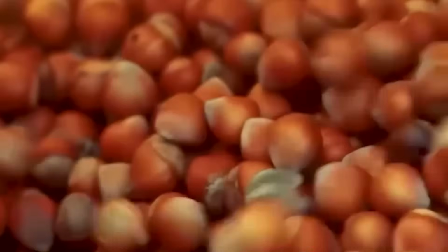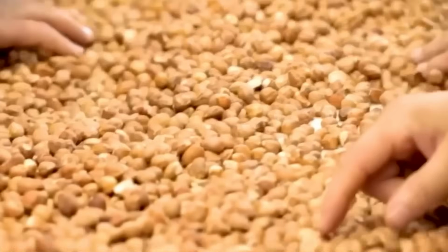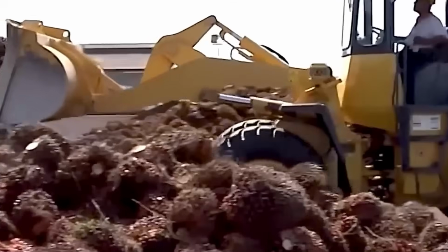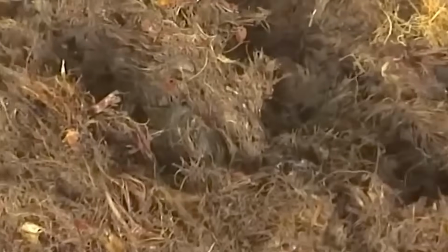Grouping is performed using star wheel collators, which align the units into rows for secondary packaging. Secondary packaging uses flat fold cartons erected via vacuum cup pick-and-place systems. Hot melt glue is applied via nozzles to predefined folding flaps, which are pressed closed by mechanical arms. Each carton receives printed labels containing product name, nutritional data, batch code, allergen information, and certification marks.